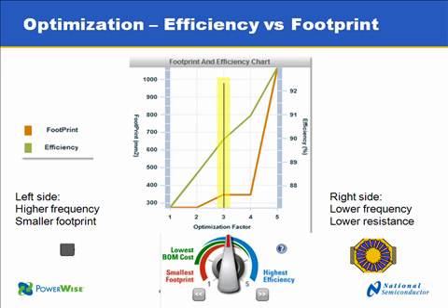And this is because we're now using higher switching frequency. And this allows us to get that inductor size down because we don't need as much inductance to maintain the ripple current. But we also increase our switching losses, our AC switching losses in the MOSFET. And so our power dissipations go up and our efficiencies go down.